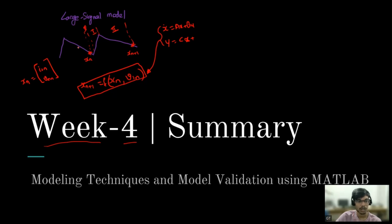The large signal model is to get this information accurately with ripple, because we are not neglecting the ripple, we are considering it. So it will give us accurate information, and then we have validated using MATLAB. So until this point, we have got the large signal model, and we have validated it, because whatever we are getting, I have to check whether it matches with the switch simulation. So this completes the large signal model.